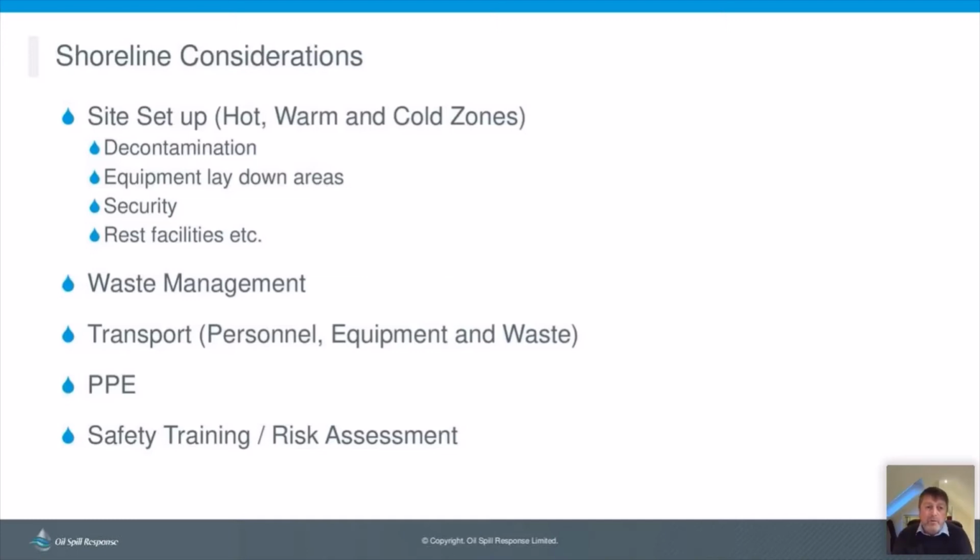And then site setup, hot, warm and cold zone. So again, having those trained supervisors on the shoreline, not necessarily all trained responders, but all trained supervisors on the shoreline. One of the things they'll be looking at will be setting up their shoreline zoning, if you like. The hot zone is where the oil is, and where your responders will be when they're working with the oil, and the equipment that's been used that's getting oiled is in the hot zone. Cold zone is where everything is clean, basically. So you can have things like catering facilities there potentially, first aid stations maybe, equipment laid down for clean equipment will be in the cold area.